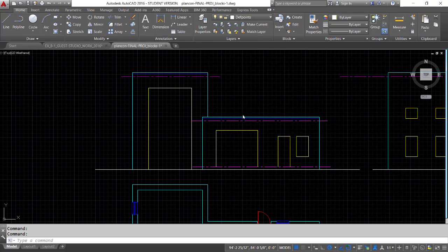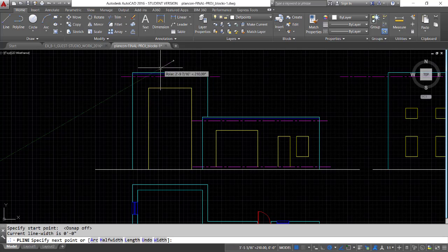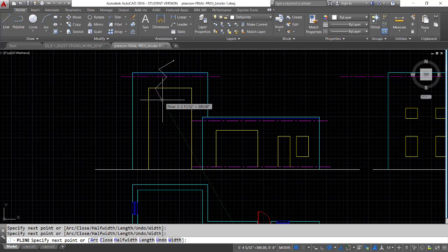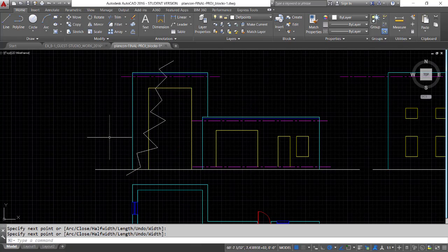So if I make the def points my active layer, and just like I did on my other elevation, the completed one, I want to create some contained areas here for where I'm going to place my hatch pattern, then I might start the polyline command, and I'm going to turn off the object snap and just drag a zigzag shape right across, and then hit enter.